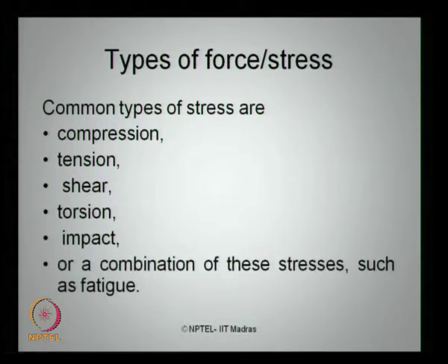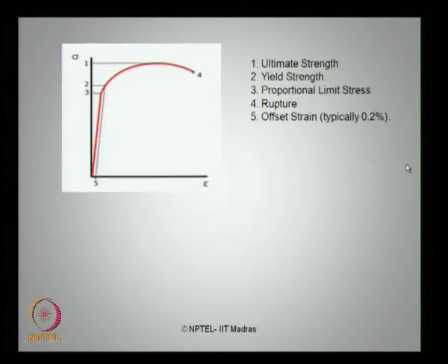And interestingly, a combination of these stresses is the most critical way we must look at them. If they act independently, or in the absence of others, then the problems are lesser, but if they combine together, then I may encounter different kinds of problems. One example is a fatigue problem, which is reversal of forces in terms of, let us say, tension and axial compression.